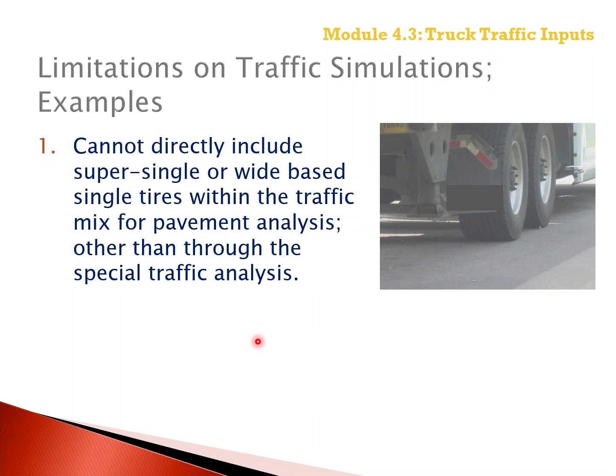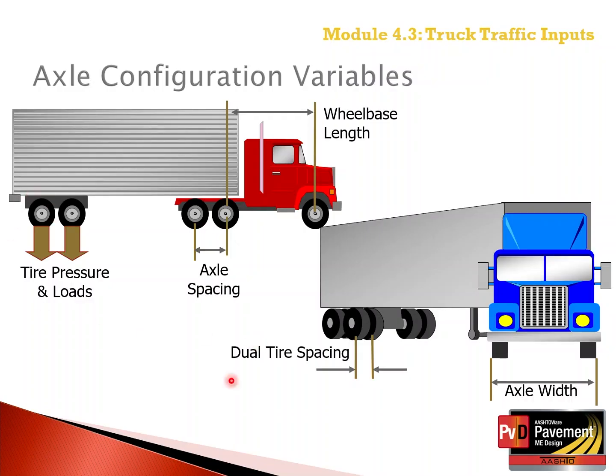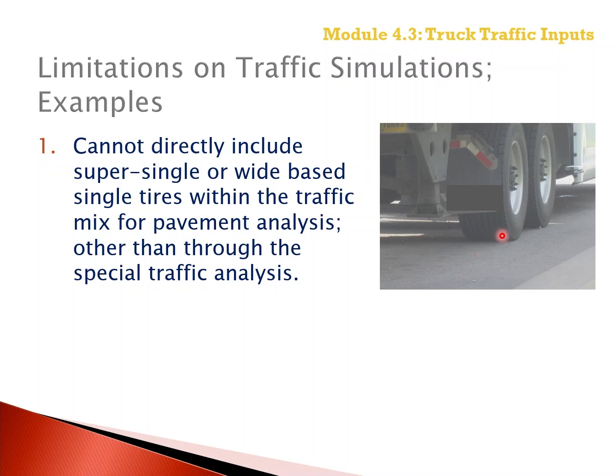So the super singles or the wide base single tires are not directly simulated within the Pavement ME software itself. They can be simulated if we assume a dual tire spacing. In other words, if we assume the dual tire spacing between the two tires to be 0, so both tire loads are then applied to the same tire.